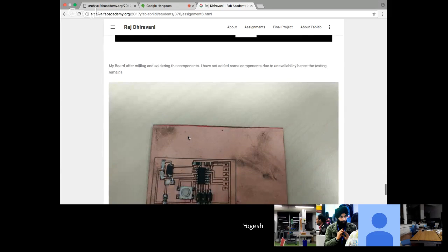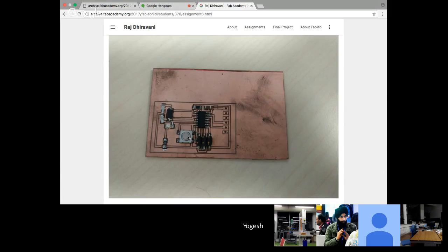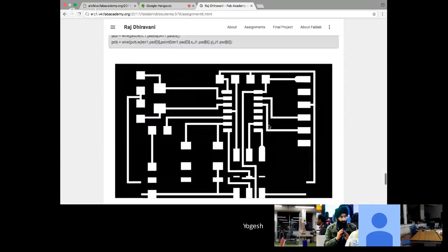So okay, what you can do is you can put the power using this connector. Yeah. This has got VCC as well as ground pins. Okay. So you can directly connect these pins to your last time's fab ISP. And then you can test the PCB at least. And then you can try reading the fuse bits and signature of the IC. You can even program it without adding that, because that is just a connector for interface for the other circuits to connect. Okay, so I can do that. So before the lectures, you should add.